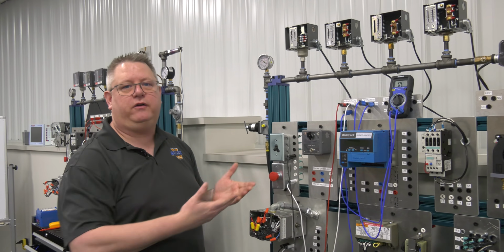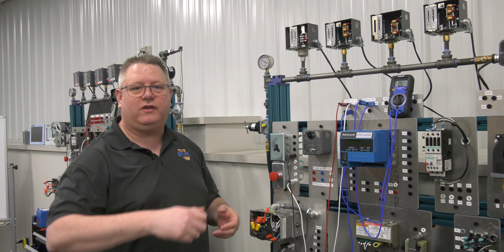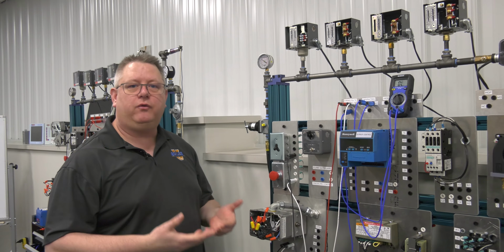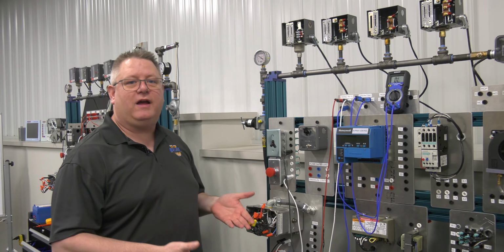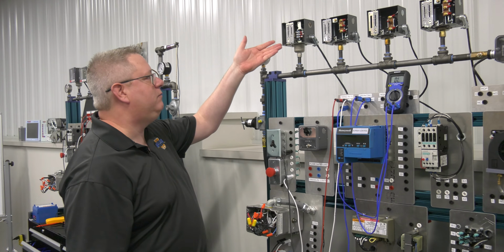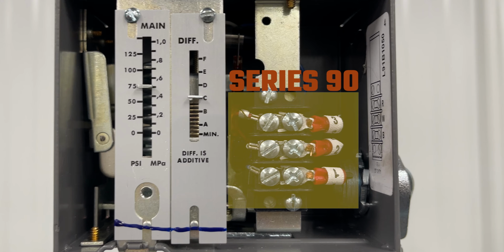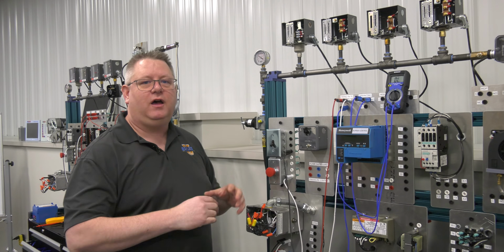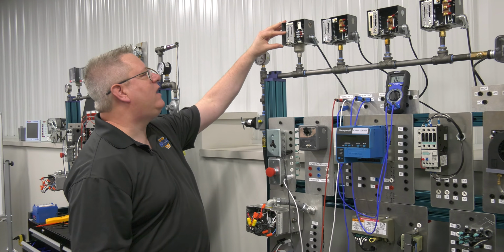This is the accelerator of the boiler. The operating limit, high limit, they're more like an ignition switch. It's actually turning the boiler off. But under a reasonable load for a boiler, we're not preferably doing that. We're actually throttling the firing rate, and that's the point of this job. So as such, this is typically wired with 3 wires in what we call a Series 90 configuration. And that's the native language of a Honeywell mod motor to receive that slide wire input on the majority of boilers. So this boiler has 2 settings on it.